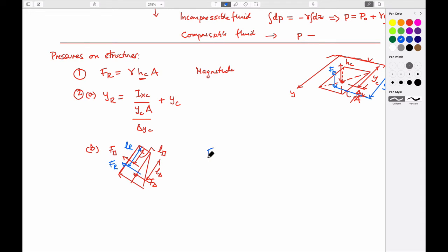And so the product of the moment for both of those, for the resultant and its location, is going to be equal to the sum of the triangular distribution and its length, plus the prismatic distribution and its length. You typically know this. For instance, if this is just a uniform distribution, this would be acting at half height, which would be this length here. If this is a triangular distribution, this would be acting at 2/3 height, so you know that.